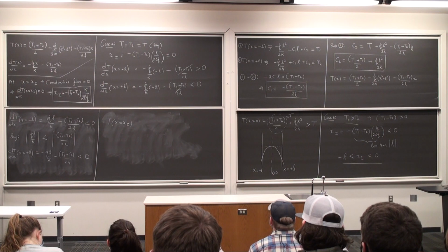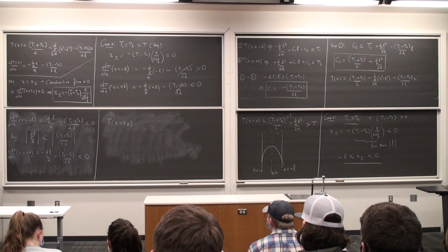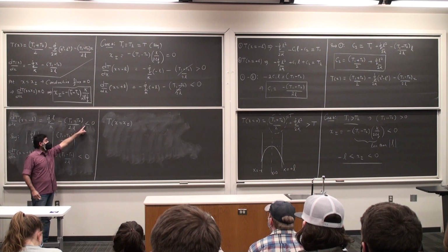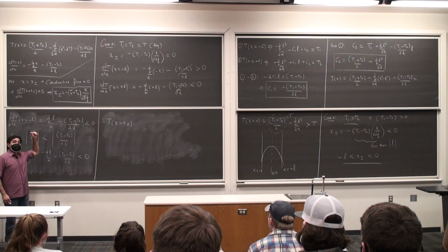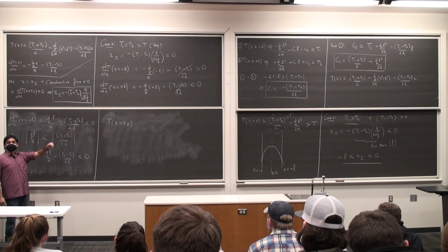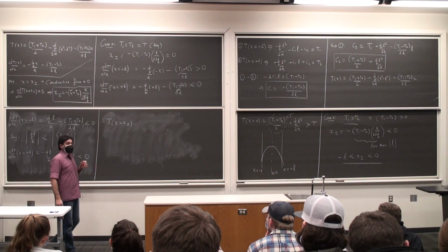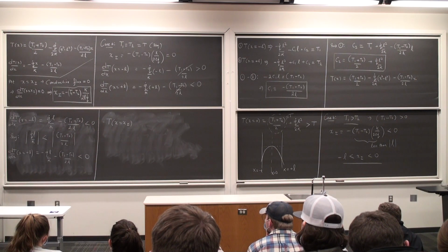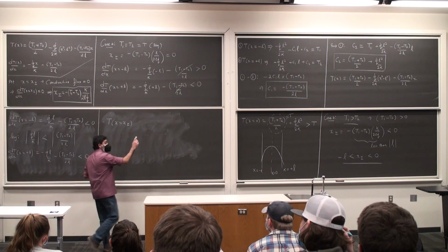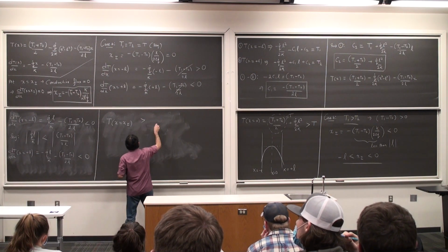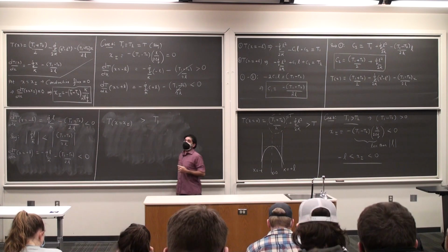Then I can have heat transfer taking place in the directions that we have just looked at. Okay, I can have heat coming in through the left side, heat coming in through the right side. If temperature gradient is less than 0, it means it is the heat coming in through that side. If temperature gradient is positive, it means heat is escaping through that side. Conductive flux is escaping through that side. Okay? If I calculate this value, and I'm not going to do the calculations, you can figure it out. I'll have it posted on my notes. This will end up being greater than T1.